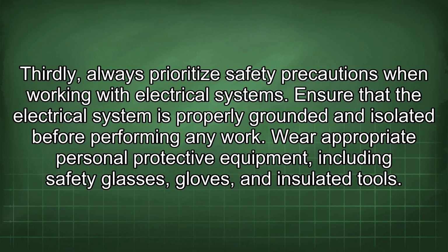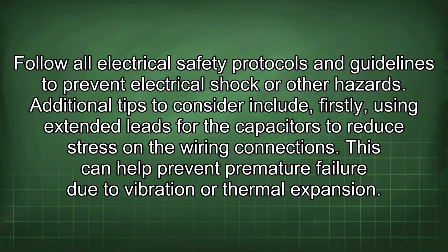Ensure that the electrical system is properly grounded and isolated before performing any work. Wear appropriate personal protective equipment, including safety glasses, gloves, and insulated tools. Follow all electrical safety protocols and guidelines to prevent electrical shock or other hazards.